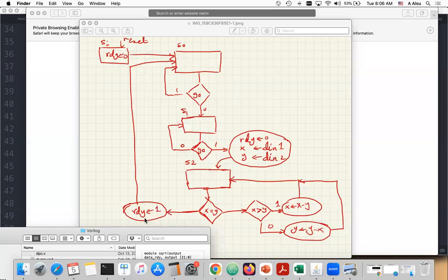Conditional box. One of the mistakes that you made in the quiz, and I noticed that this is a common mistake, is that you use a Mealy box right after a state box. This is wrong. A Mealy box needs to be preceded by a decision box, otherwise it has no business to appear.